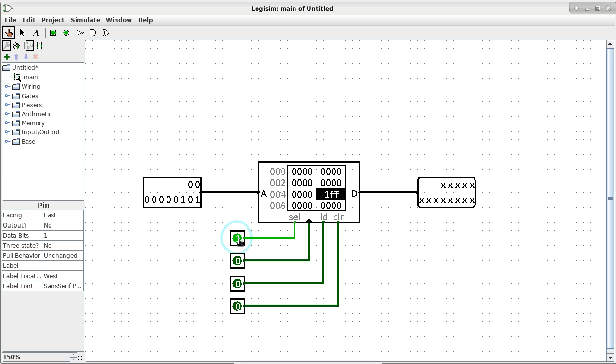Well, that's because the LD pin, if it is a 1, specifies a read operation. When I specify a read operation, we are reading from RAM. Right now, it has a 0, which means we are proposing that we are writing to RAM, which is not what we want, okay? We want to read from RAM. So the other thing we have to do now is to put a 1 here, and you can see as soon as we turn the LD pin into a 1, which specifies a read operation, the output, which is the D port at this point, becomes all ones, because that's what we specified with 1FFF. That's 13 ones. So that's how we read a location in RAM.